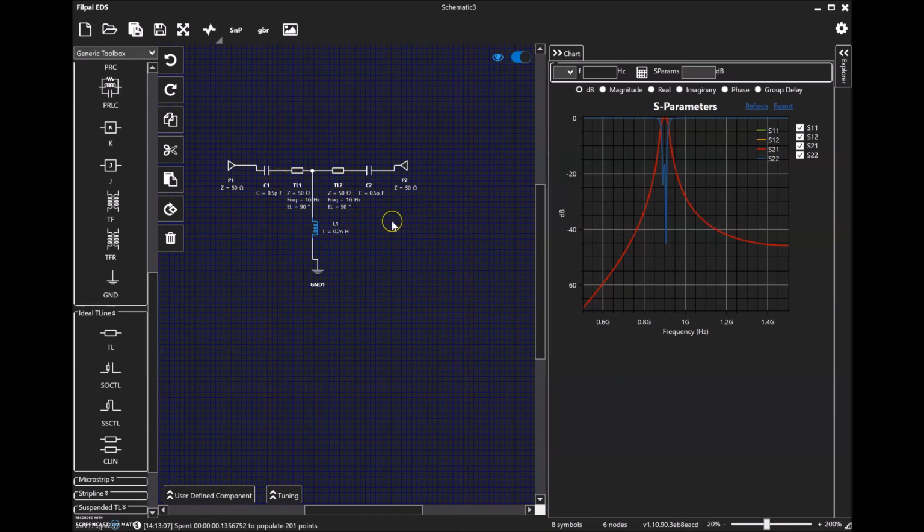In other words, we can have the same physical dimensions of 180 degrees electrical length. By adding an inductor, we are able to produce two resonances rather than one. So this helps to reduce the circuit size or the layout in practical implementations.